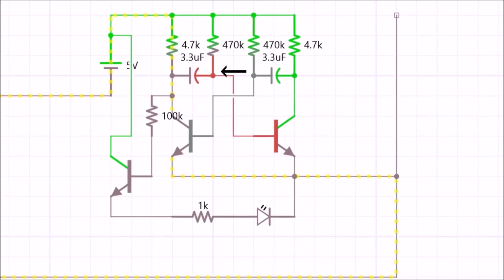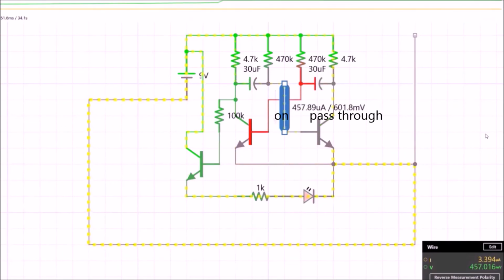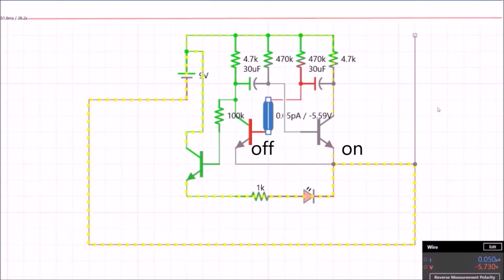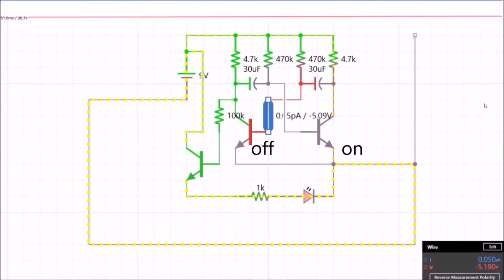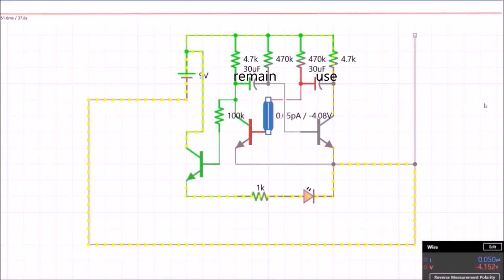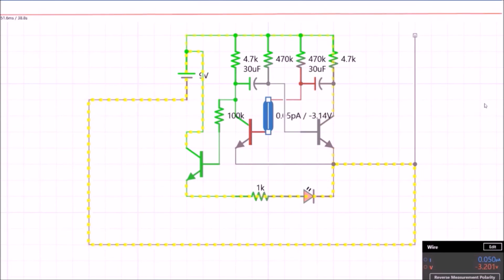This will eventually get to a point where it turns on the right transistor and allows a sudden electricity pulse to pass through. That causes the right transistor to turn on and use electricity on the right side of the right capacitor, which turns off the left transistor. Because if the left transistor is off, more electricity will remain in the left capacitor, and will let the right transistor get more electricity on its base, and so on. The net effect is that the left and right transistors flip states.